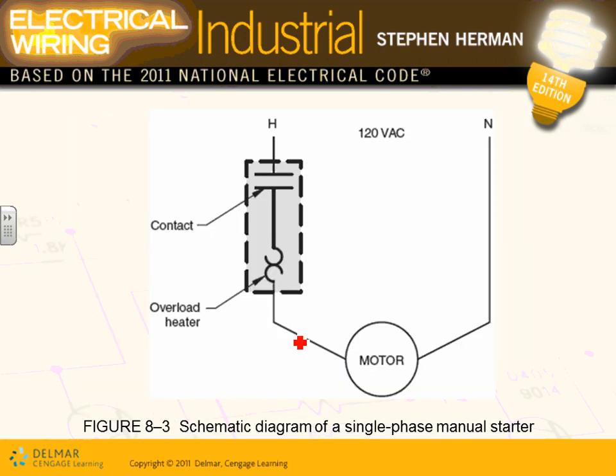That's your manual. Now also you have a manual for single phase. They have a manual that looks like this. So these contacts, guys, you have to interfere in order to turn them on and off. I want to bring to your attention the symbol that they use for the overload. If that air handling unit is overloaded, it will trip and open the contacts to de-energize the motor. That contactor is manually operated. That's the schematic diagram for manual start. I can't emphasize the word manual enough. These contacts here are not driven by a coil. They're driven by push, by your foot or your finger or your hand.